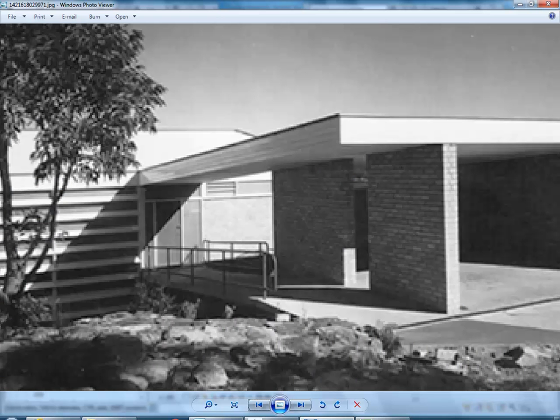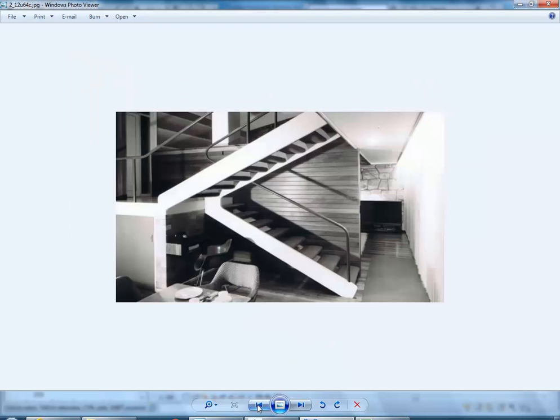Okay, so looking at the interior, has anyone had a look at the stairs and counted the rises? Probably haven't gotten that far yet, but no, okay, so I'll count them for you. 1, 2, 3, 4, 5, 6, 7, 8, 9 rises to the landing, and then 1, 2, 3, 4, 5, 6, 7, 8, 9 rises to the level above, which makes life easy. If they're even, then the landing should be exactly in between.